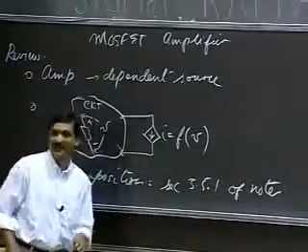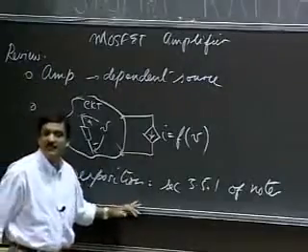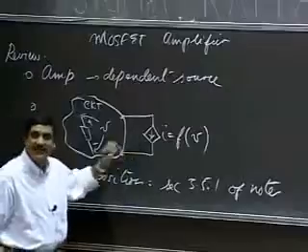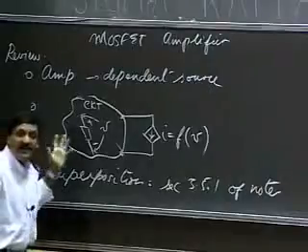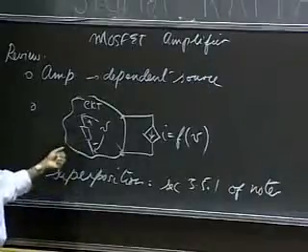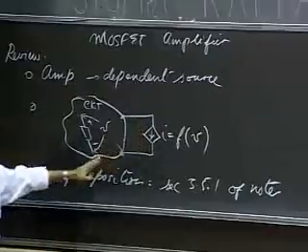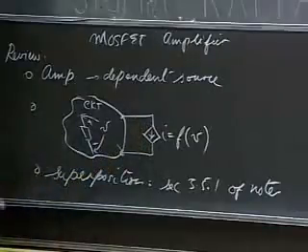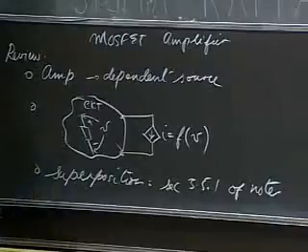The approach is very simple, actually. For the purpose of superposition, do not treat your dependent sources as sources that you turn on and turn off. When you do superposition with dependent sources, simply leave all your dependent sources in the circuit, and turn on and off only your independent sources.